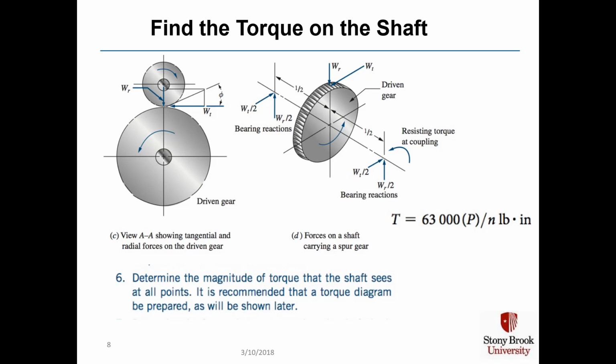If there's only one other mechanical element present, then the torque on that mechanical element, which is the torque out, is going to be the torque in from the motor. Otherwise, the torque gets split up based on the relative diameters of the different pulleys and sprockets and gears that are on the shaft and on the mating shafts.